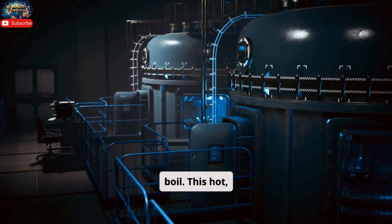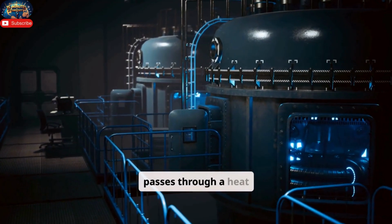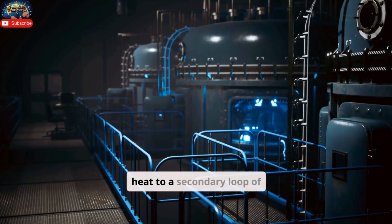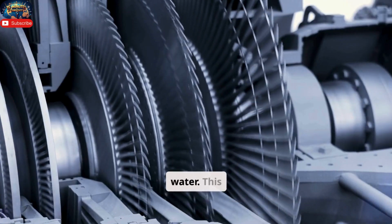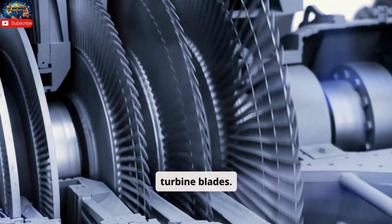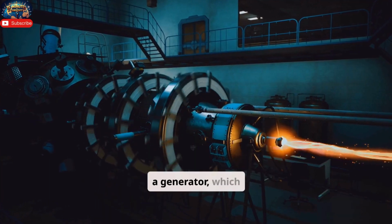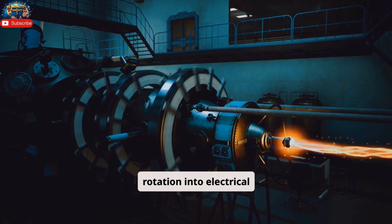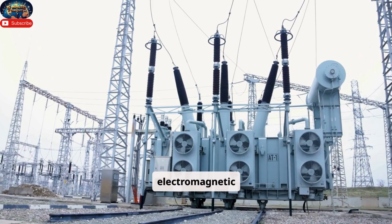This hot, pressurized water then passes through a heat exchanger, or steam generator, where it transfers its heat to a secondary loop of water. This second loop boils and produces steam that spins the turbine blades. The turbine is connected to a generator, which converts the mechanical rotation into electrical energy through electromagnetic induction.